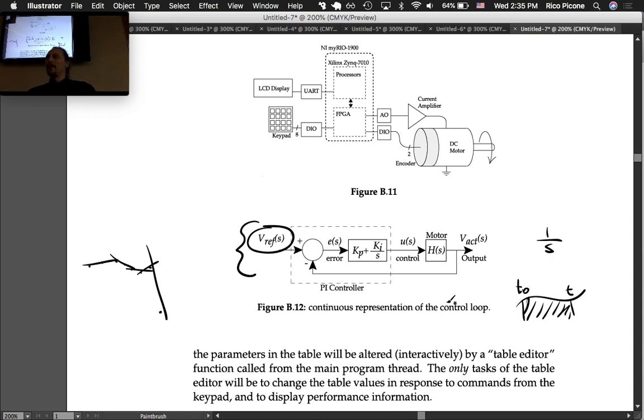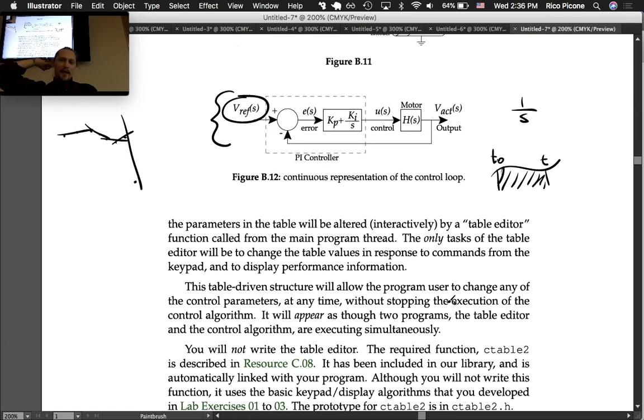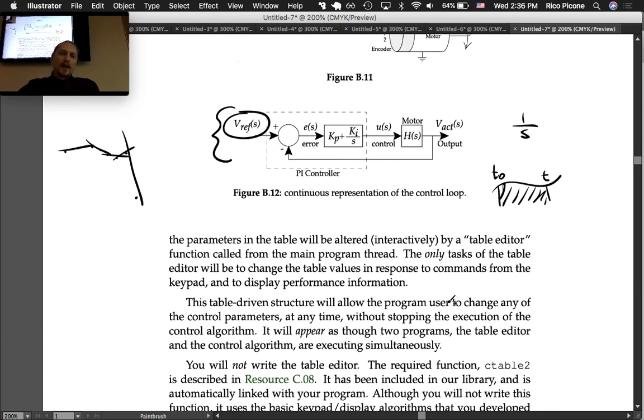Say it's too far right for a while, it accumulates, and then suddenly maybe some obstruction is removed. It's got all this integral windup built up, and then it just way overcorrects. So you've got to watch out for that too. Okay, so PID control, PI control in this case, really useful, and maybe we'll have some supplementary discussions on PID control.